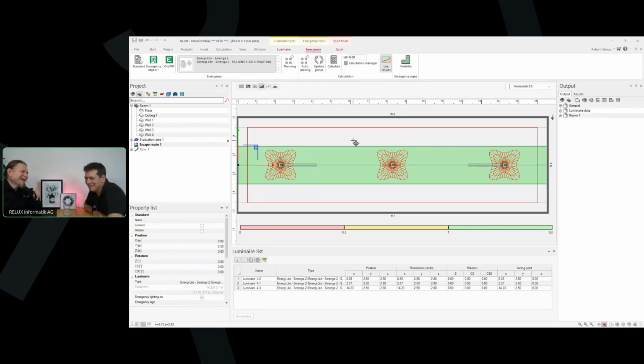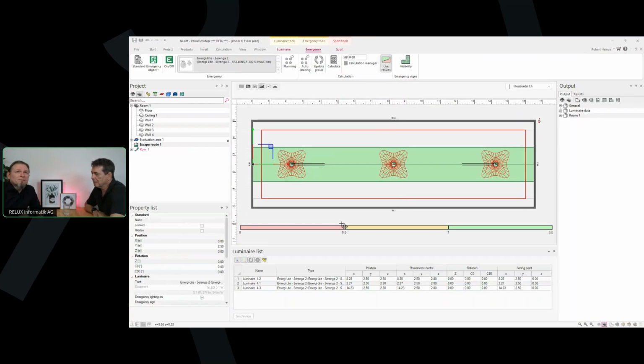Yeah, there's this small update problem from switching from the old standard to the new one. But it was good to see the yellow, that it's existing and that it is working. The problem in general will be that, according to the new standard, you maybe need more luminaires than according to the old one. Not in any case, because in many cases you have enough area around, but in general you may need more luminaires.